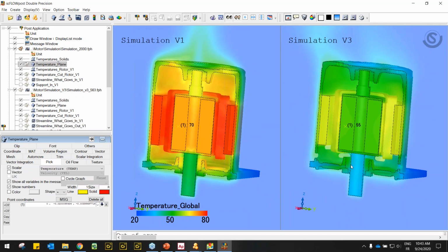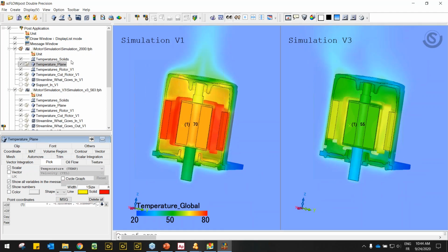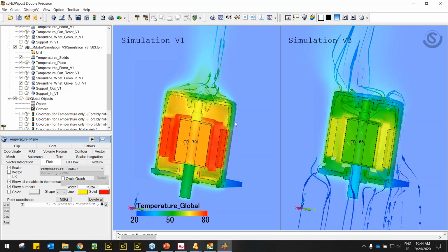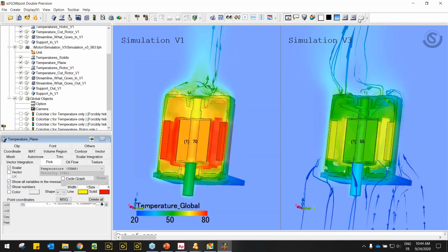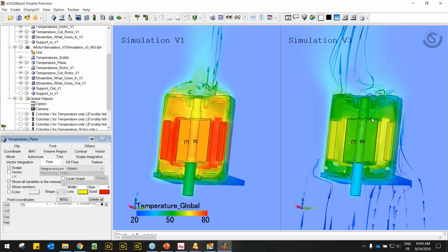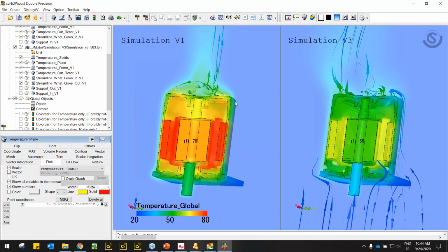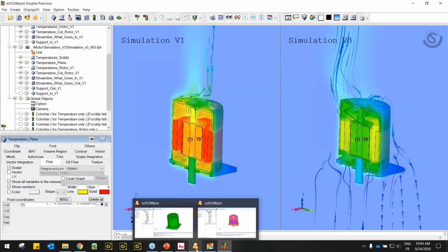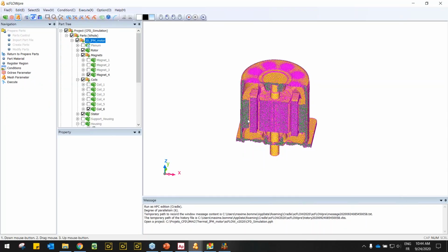Maybe you can do something better, because maybe for dust consideration and so on, it's maybe not the best solution, but you can act. So if I summarize, you import your first design, then you run a first calculation. The software tells you a status about the temperature distribution. Then you can also get an insight to know why you have this statement in temperature distribution. So in this case, as you can see, we had some hot air trapped inside the motor. By creating these openings, we can see that now we have some fresh air coming inside the motor and going out. So it's logical, but it's always difficult to quantify. So that's why I think you need CFD, and that's why I also think that scFLOW is a convenient tool for you. So that's all for me.